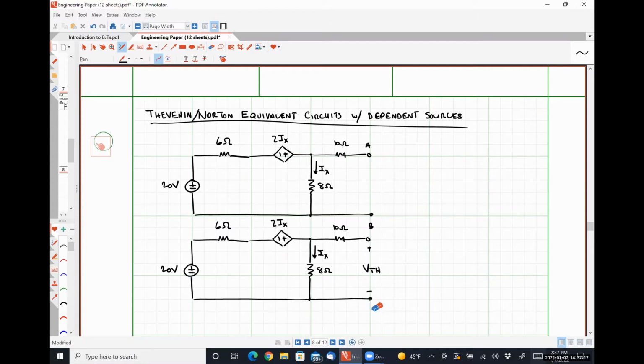So you would be able to know the voltage drop over the 8-ohm resistor. And then Norman, I believe you said, and then the 10. Could you clarify what you mean by and then the 10? So the voltage drop over the 10-ohm resistor is 0. I agree with that. Could you elaborate as to why? And we talked about this a couple of times in the last class. Exactly right. There's no current flowing through the 10-ohm resistor, which means there can be no voltage drop over the 10-ohm resistor. So in reality, the Thevenin voltage in this circuit represents the voltage drop over the 8-ohm resistor.